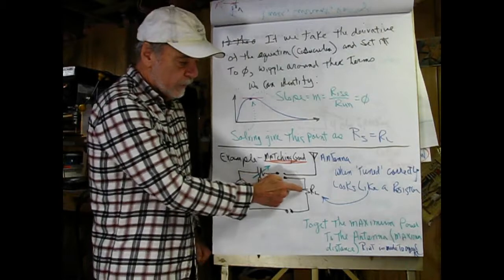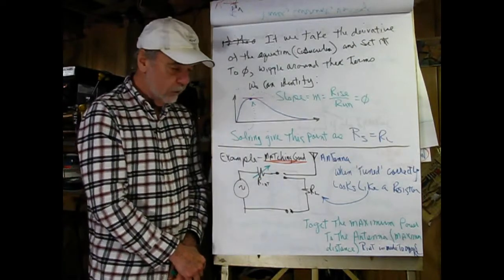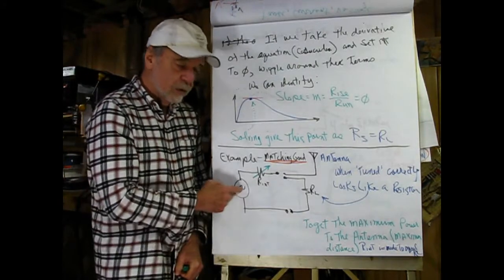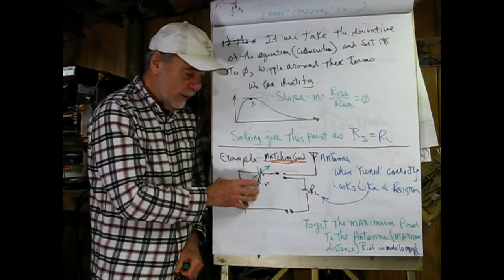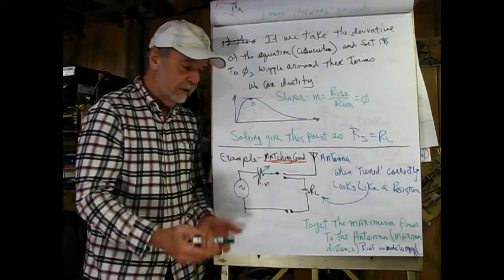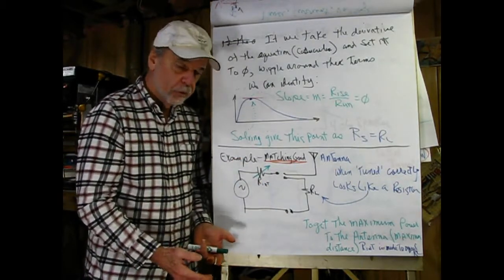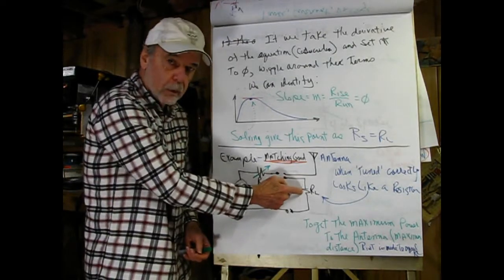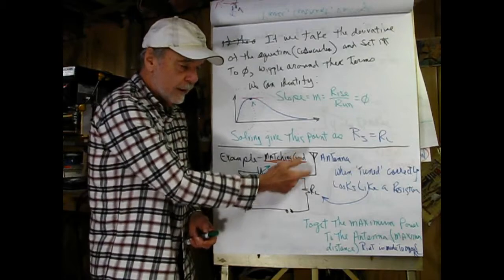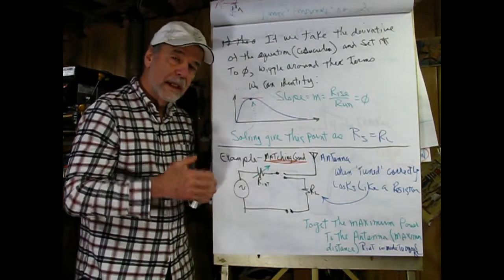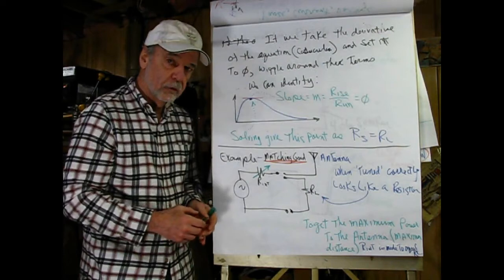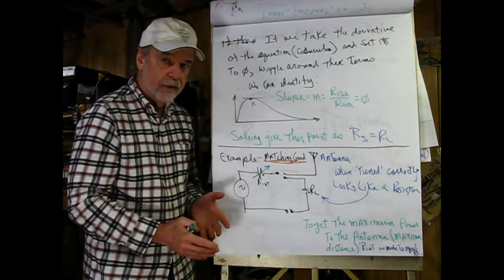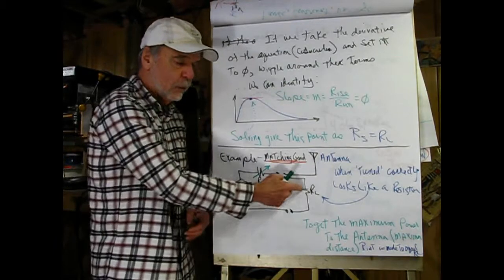So we're just going to pretend here that our antenna is a load resistance, and our desire would be to maximize the power that's being created by the source, which is a collection of transistors and tuning coils and capacitors and whatever, to the load, so that the power reaching the antenna is the greatest, so the range from the base station is the greatest. Now, that's a very good example where matching is a good thing. We want to get the maximum power into the load.